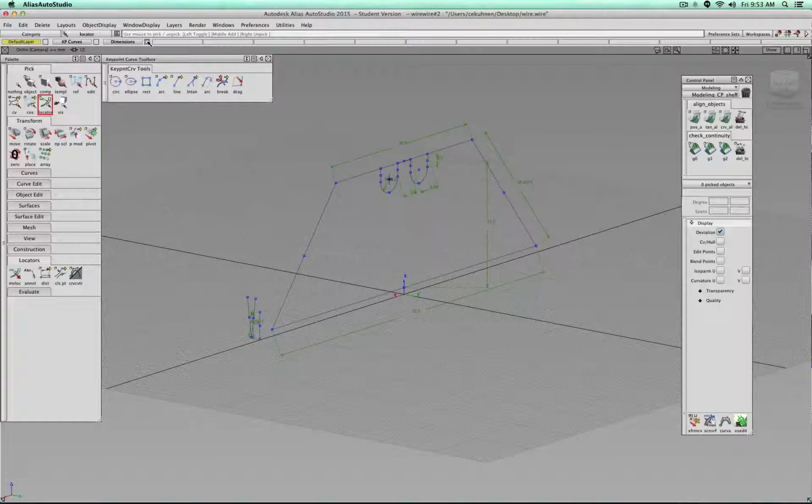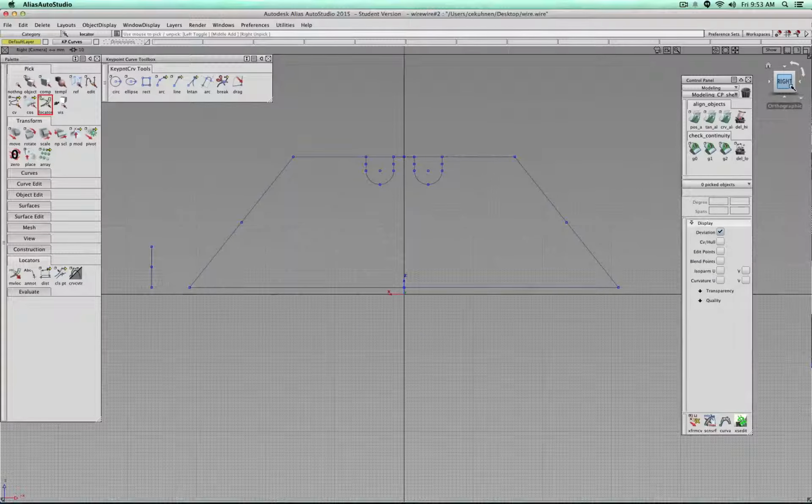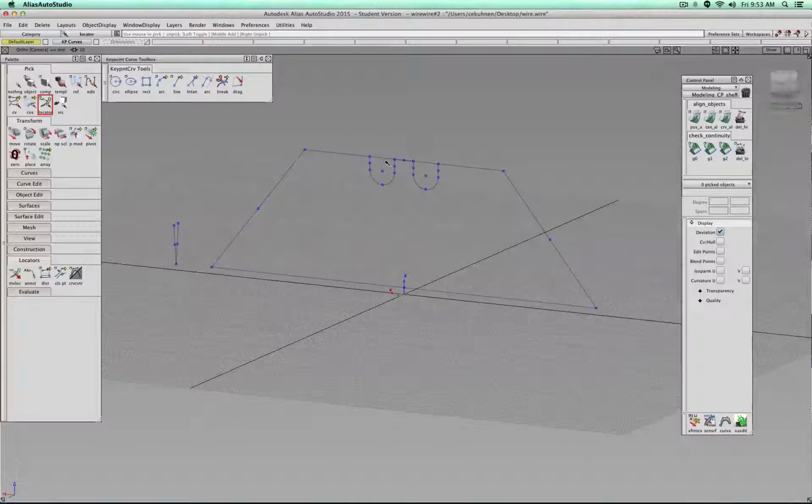Try to always structure your designs so that it's going to be easy to show information you need and not get confused. And for example, like when we create surfaces, you want at one point then when we have the surfaces to hide all the stuff because you don't want the surfacing tools by accident continuing clicking on these lines.